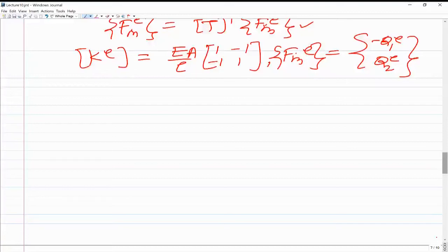Let's say there is a hydrostatic pressure from the outside, which ultimately would be transferred to the stiffeners and rings as a transverse load. So if we want to model those rings and stiffeners, we will have to use what we call beam elements.